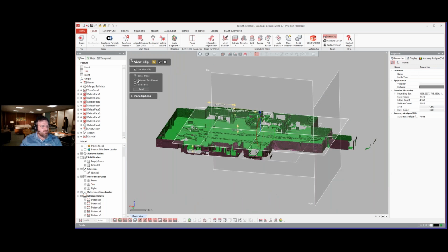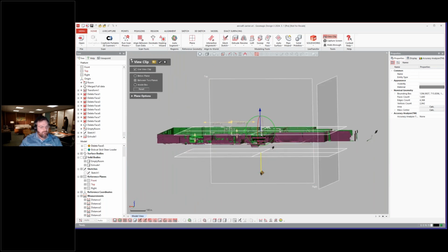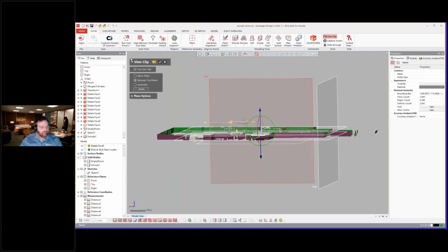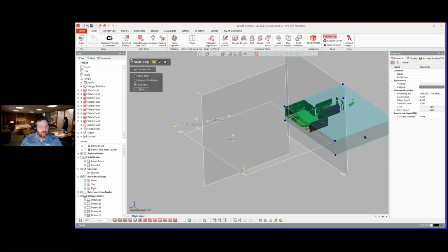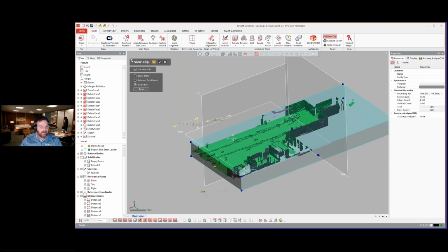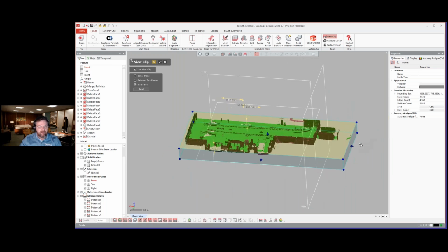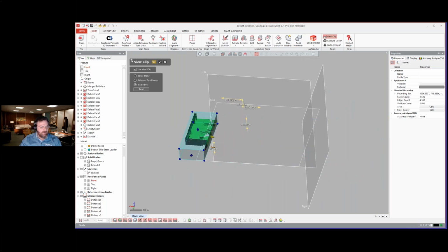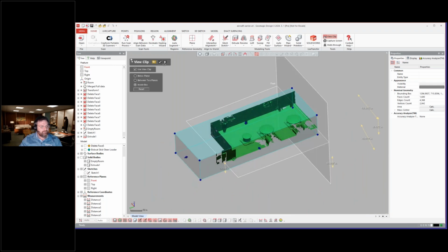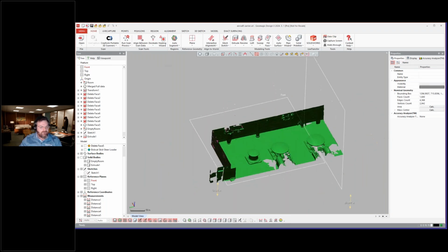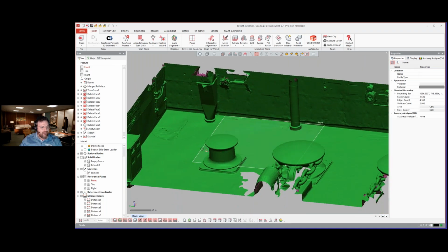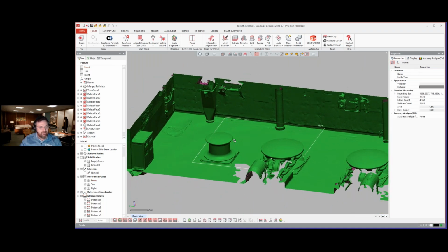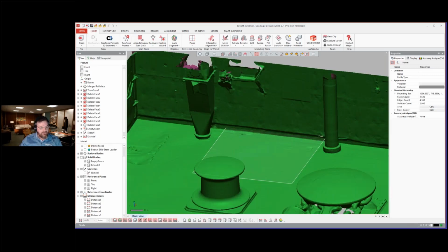You see between two planes, I can set it to be between the two planes to take the floor away as well, or inside of the box is what we were talking about before. So you can just manipulate and move this box around to locate a different area. We'll just set this and accept it so you can see what it looks like when we're done. So you can set your view clip, hit OK. If I just want to work with this area right now and not visualize anything else, and model things or bring things in, I can do so by just using this view clip.